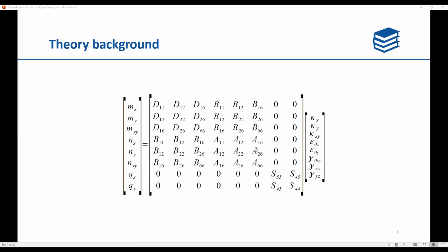All right, so here in the middle, we have the new stiffness matrix. It's the exact same size as before, so the laminated shells are compatible with the other objects in FEM-Design, but it contains this new submatrix B over here and here to achieve the coupling effect or the eccentricity part for non-symmetric panels.